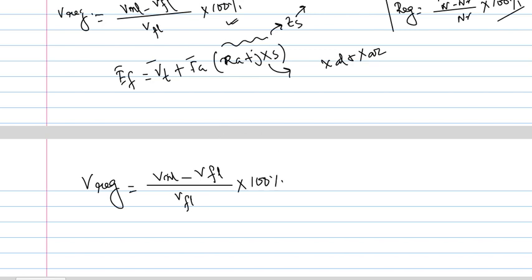And always remember that these voltages are magnitudes, because a voltage is a complex parameter. If you represent it in polar coordinates, you will find one is the magnitude part and the other is the angle part. So always remember to take only the magnitude part to put these values. All these values are magnitudes, and it is a common mistake made by students.